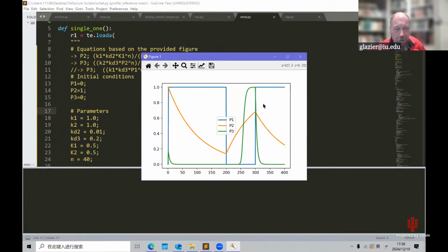Yeah, there we go. So here, P1, P2 starts turning off. By the time P2 is okay, why does P3 not come up? That's what I'm puzzled by. It comes up a bit, but not a lot. Now on the second phase, after you pulse it, it does. And that's because we're using an AND instead of an OR.